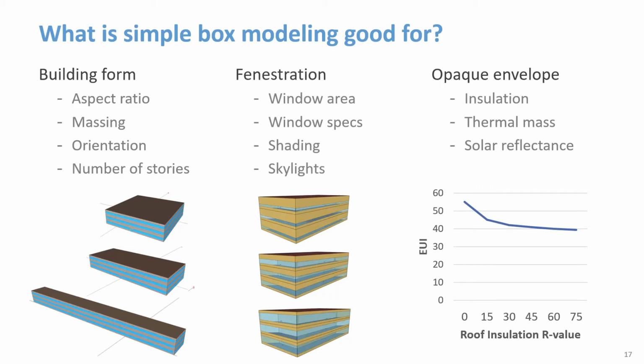Well, they're important, first of all. They affect the thermal loads, which affects HVAC sizing and energy consumption. And second, many of these decisions are made early. So you need a quick, simple method to do the analysis. Third, energy models do a good job at these things. That's what energy simulation programs are really designed for. And fourth, it's hard to evaluate the performance impact of these types of measures except with an energy model. So these are all relative performance analyses comparing alternatives, which is a great application for energy simulation.